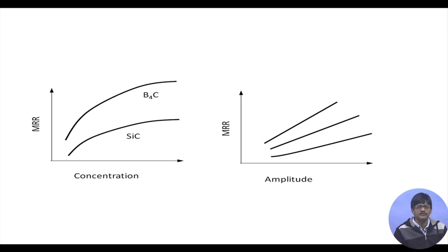You know, f to the power 3/4 divided by sigma w to the power 3/4 into 1 plus lambda to the power 3/4, into amplitude to the power 3/4, into grit diameter, into frequency and all those terms. There is no term of abrasive hardness or strength, nothing of the abrasives except abrasive size. So, material properties are not included. So, why should there be a difference?